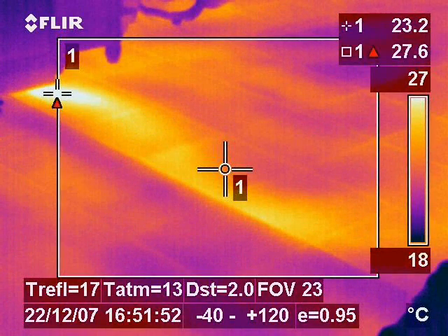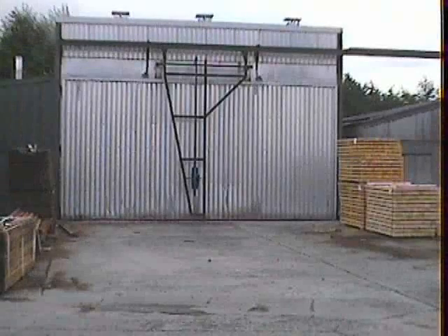This image was recorded when a client approached us to help find a burst heating pipe. The thermal image shows the source of the burst pipe, but this was not where the water was rising and therefore couldn't have been found easily otherwise without a lot of excavation.